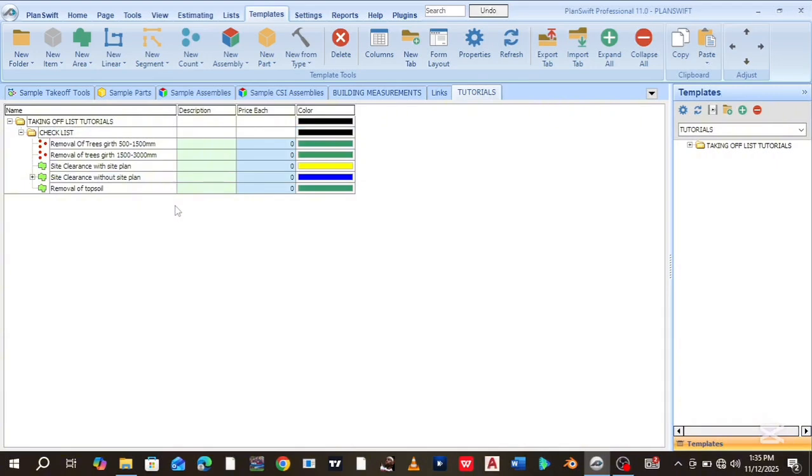Now I am going to be teaching you two ways you can go about creating templates for column pit excavation. So I want you to pay attention while this video is going on, because this video is going to be very rich in information. You all know that the unit for measuring column pit excavation is cubic meters, meaning volume. And like I said before, when you want to measure anything volume, there is no particular tool here that is specifically for volume. So we have to be wise and use the area tool.